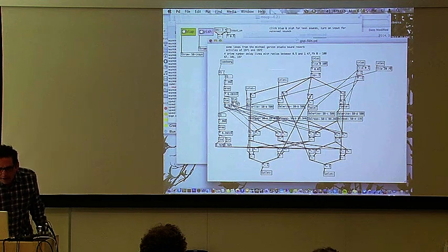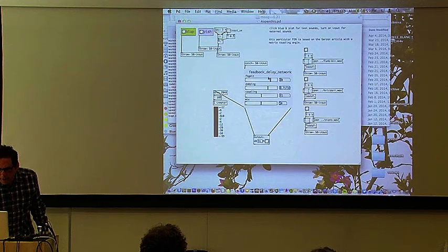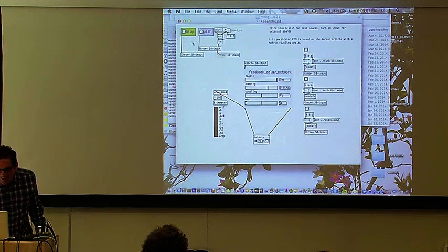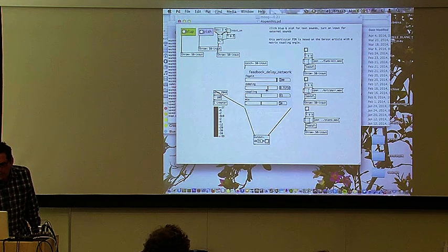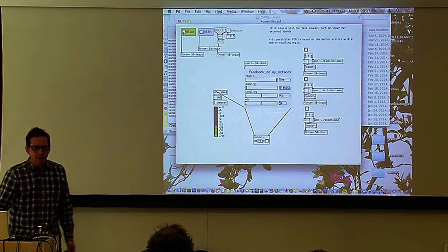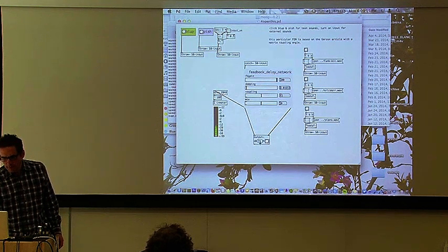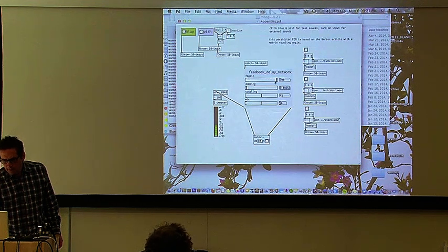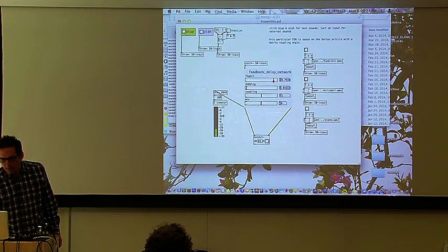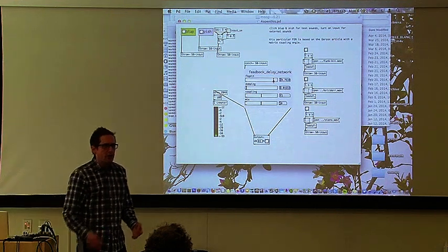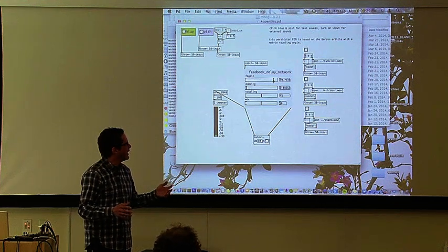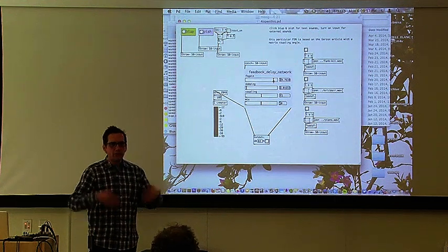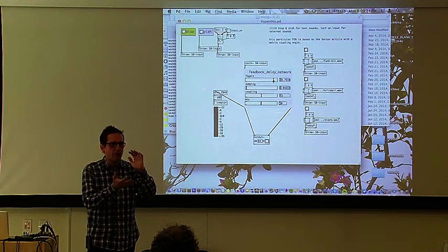And the other thing you'll notice with this network is if we turn up the feedback gain, and I'll turn down the output, don't worry. We can now put a tone in it, and let me turn the damping down. And this will just sustain. And then when we bring the gain down, we get a nice exponential decay. So one nice thing about this closed loop design is we can really control how the sound decays.